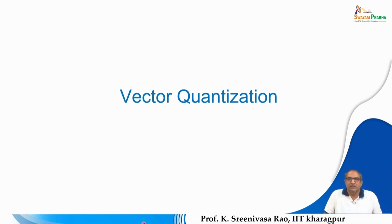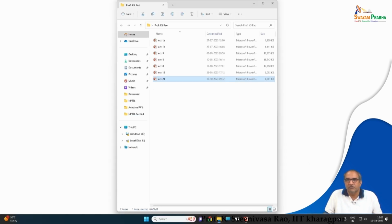So that way the linear prediction coefficients can also be viewed as the features or the representation of speech for applications like synthesis and so on. But the linear prediction coefficients are very sensitive. So if you want to use the linear prediction coefficients or knowledge from the LP spectrum for various speech tasks, we need to use its cepstral representation. The computation process of the linear prediction cepstral coefficients,